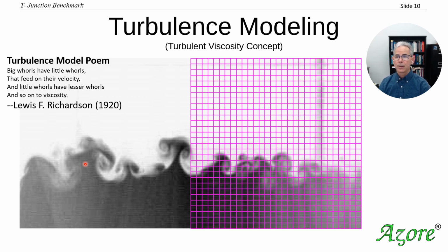And there are some people that are actually doing that, and it's a technique called direct numerical simulation. In those, it's trying to capture all of the whirls right here at the big length scale all the way down. And so then really you're only left with the viscosity representation there. So you're directly solving the Navier-Stokes equations. But that requires significant compute resources, and so there's only a very limited set of problems that can be solved using those methods because of the limitations on the compute hardware.